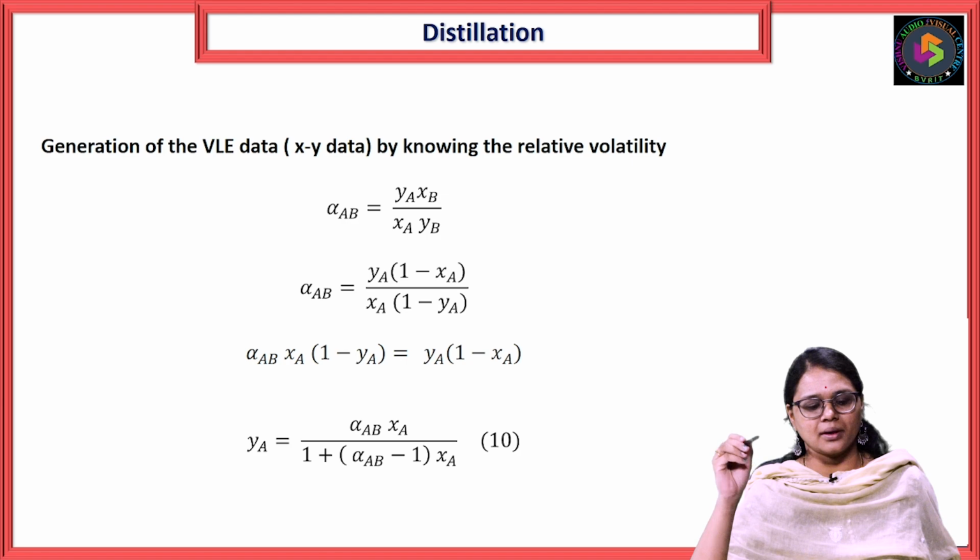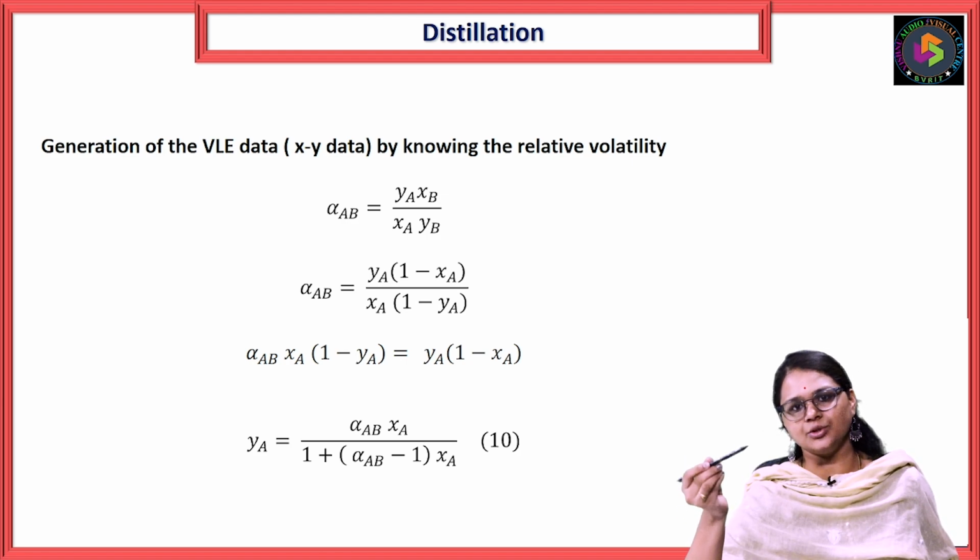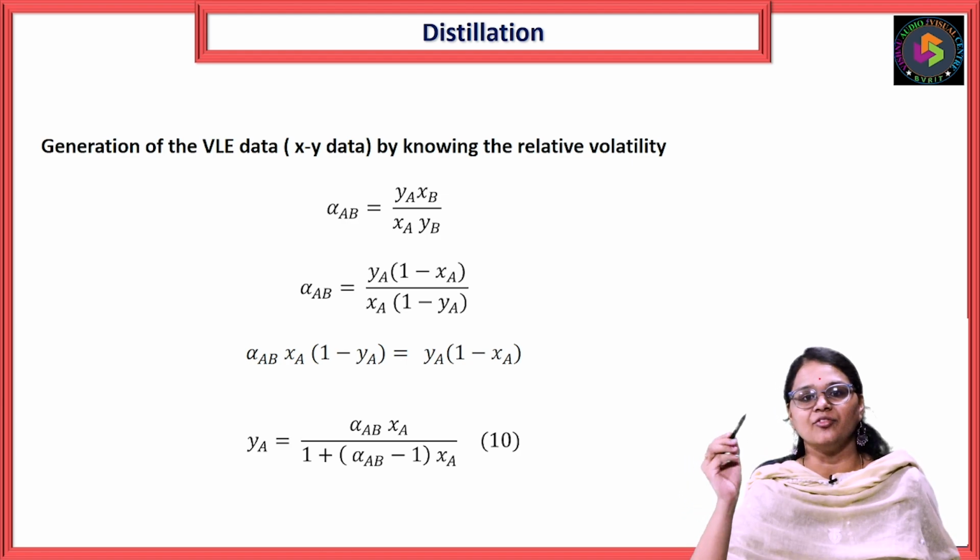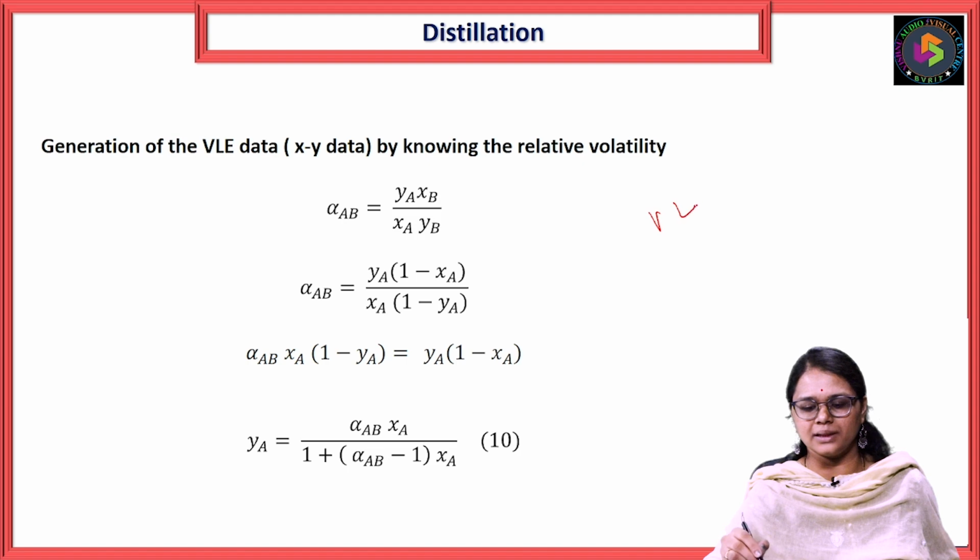From this relative volatility, you can also generate the VLE data, vapor liquid equilibrium. That means you can generate X versus Y data.